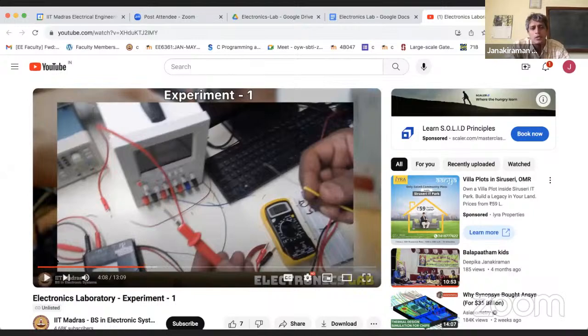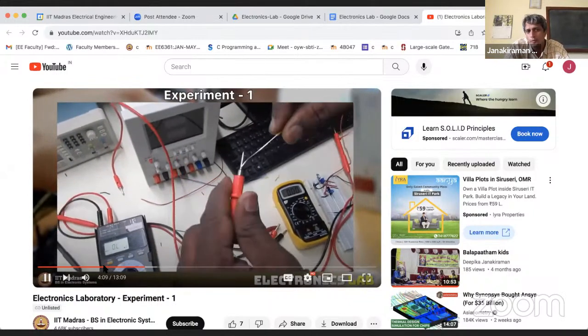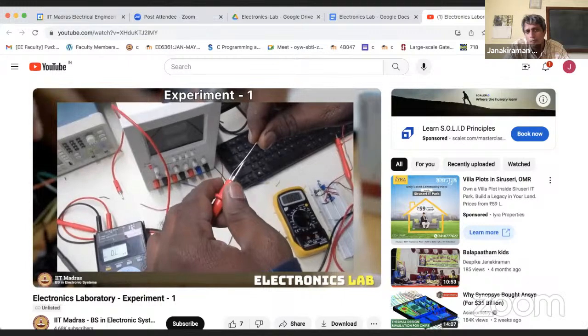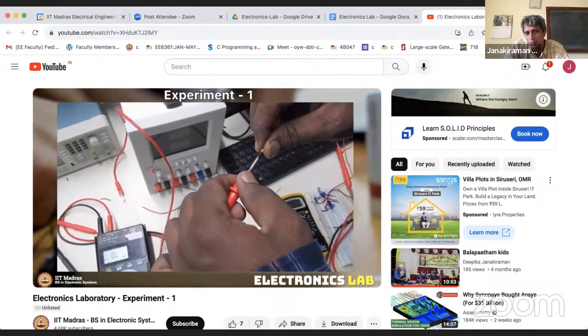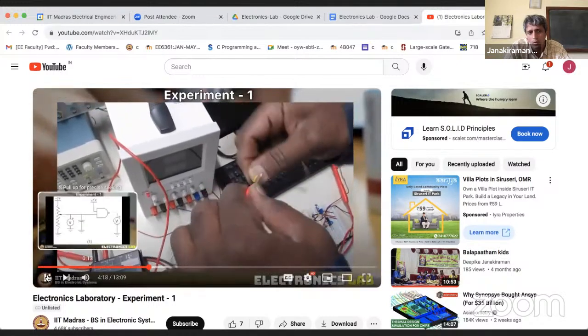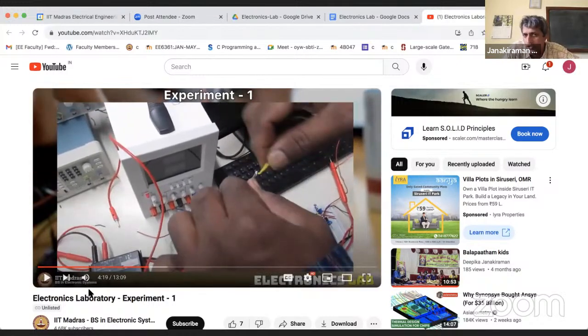Yeah. So in this part of the video, we tell you how to make one. Strip the wire off and make sure you strip it significantly this time so that you can align the wire along the metal. If you notice here, I am telling you how to make a probe wire connection, because that wire you will have to plug into the breadboard in order to make a measurement with your multimeter. So I am telling you how to cut the wire so that you can make that probe wire measurement and all those details.